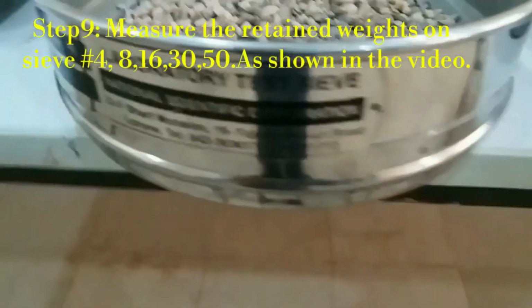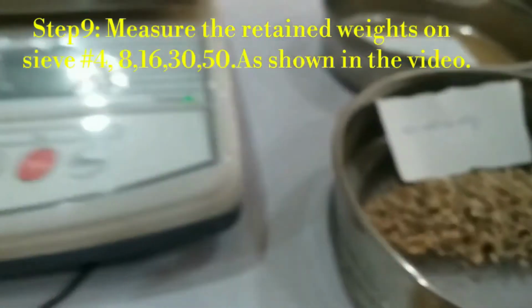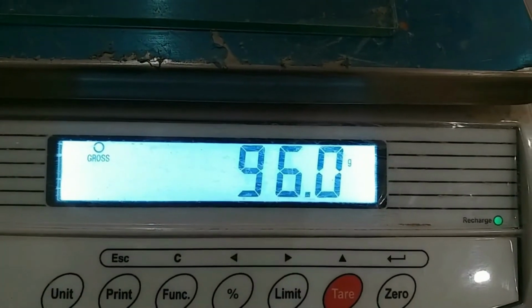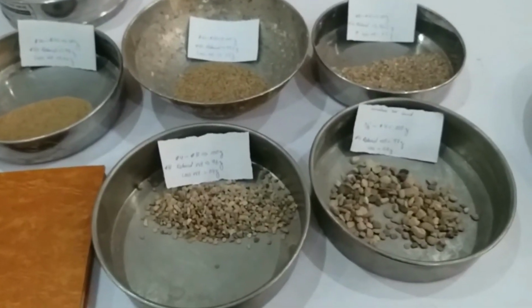हमने पास किया है, ये आप देखें ये 8 नंबर की सीव से। तो अब हम इसके ऊपर जो रिटेन आया है उसका हम वेट करेंगे, उससे जो है हमारे लॉस एग्रीगेट्स आ जाएंगे, यानी कि जितना सैंड लॉस हुई है उसका वेट आ जाएगा। ये देखें 96 ग्राम जो है वो इस सीव का रिटेन आ गया हमारे पास।